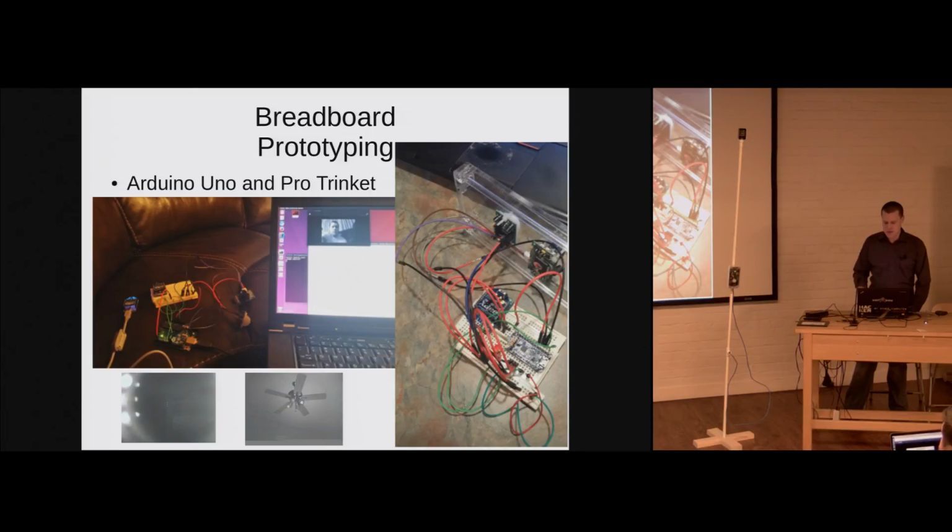And I started to put together a case, which you can kind of see on the right. It's basically the setup here. I have the plastic box with the motion detector and the camera on it. And one of the problems I ran into early on was the motion detector can't actually detect motion through the clear plastic. So I ended up having to drill a hole through there and silicone it up to waterproof it.